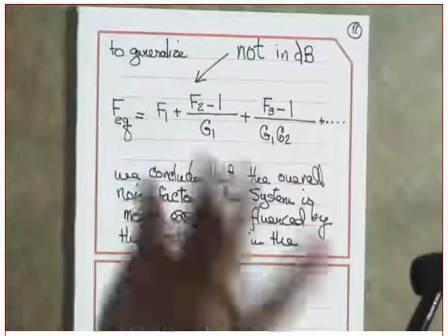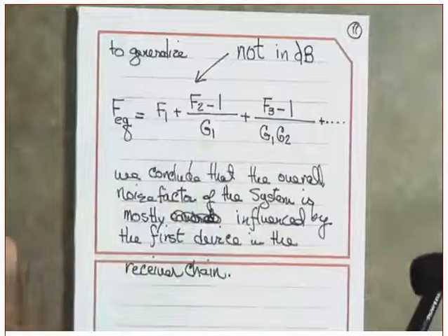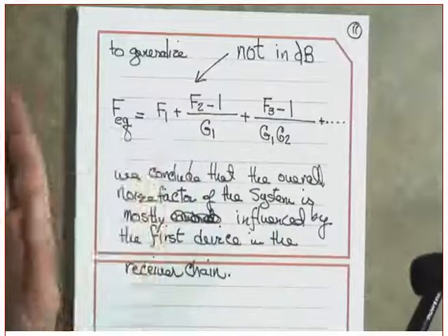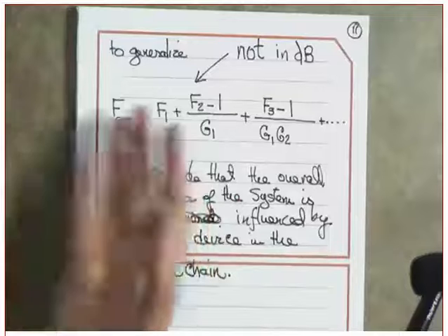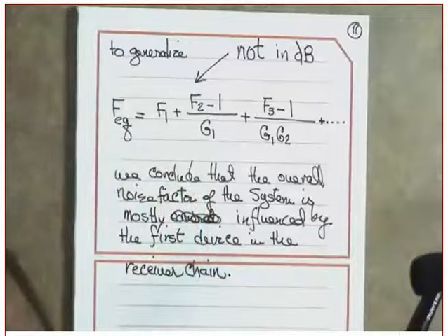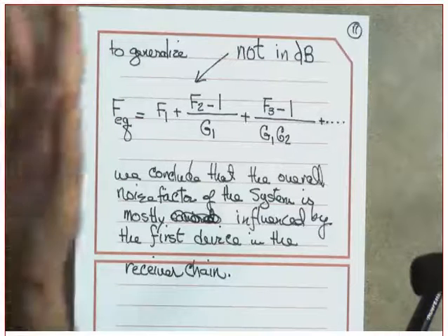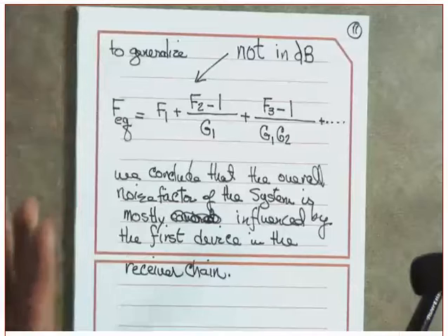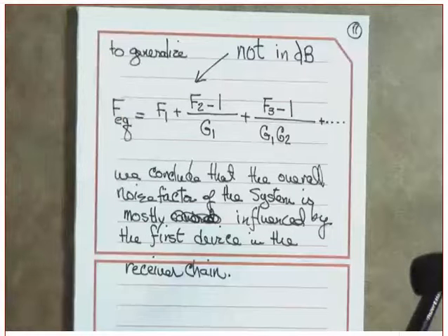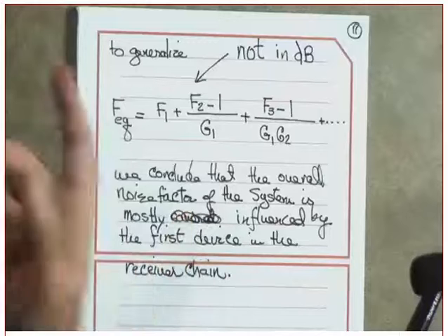The received signal is weak anyway. Can I increase it right away? We saw last time that if you put all the gain in one unit in the front end of your receiver, the front end will go into saturation. If there are blocking signals in the vicinity of the desired receiver, they will cause interference on the same frequency as the desired signal. You will desensitize your receiver. Did you get this or not? Okay. Now, what is the first device?